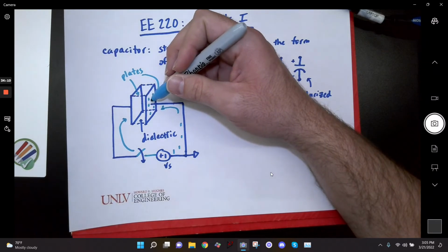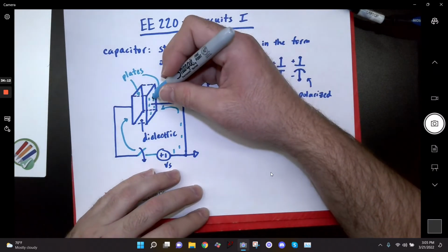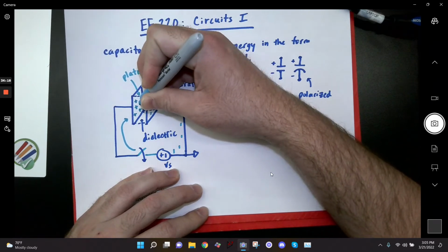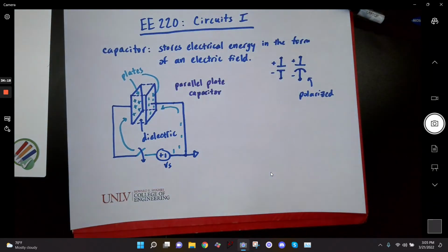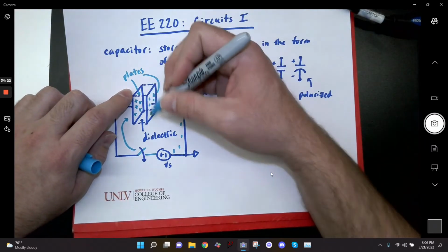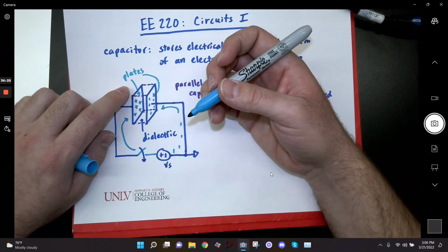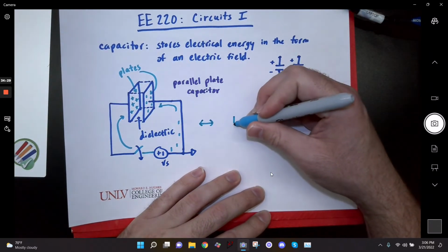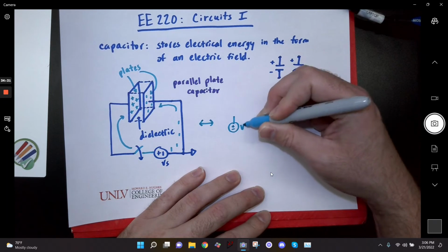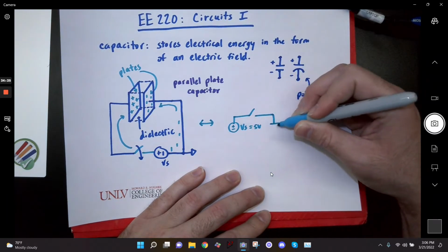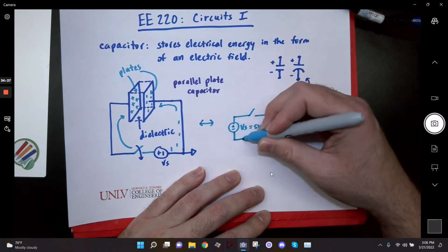of the capacitor, right? Well, these electrons attract positive charges to this plate of the capacitor, and so that will continue to happen until the potential of this capacitor matches whatever Vs is. Okay, so if I were to redraw this circuit after the switch is closed, I would draw it like this, and let's say Vs was equal to 5 volts, and then this is my capacitor, right?